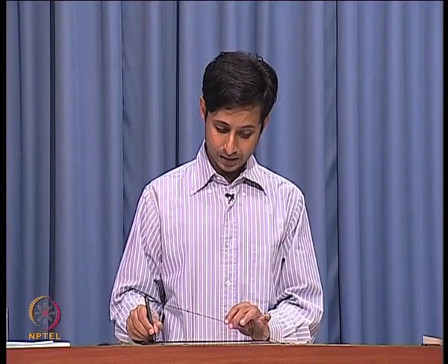So, what happens? You increase the bandwidth by a factor which is the loop gain of the system, right, loop gain of the system. Okay. So, shunt series feedback is also routinely used in a lot of different scenarios. These are used as wideband amplifiers. In fact, these are used at the input of oscilloscopes routinely. Oscilloscopes have to be wideband instruments.